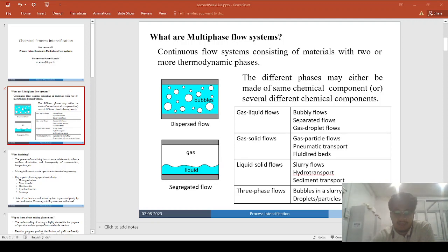So that is the same idea here. And in addition to these curved channels, a straight channel is often not suited for connecting a microflow domain to the external world. The secondary flow, called the Dean flow, as we have discussed in the previous session, also due to the curved path, perpendicular to the main flow direction, induced by the inertial forces, is a factor for process intensification.